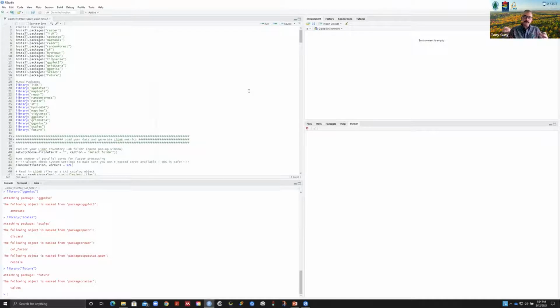So that's something that we've been doing more recently, where you use something called principal component analysis, and you run a PCA on the LiDAR point cloud, basically the grid metrics from the LiDAR point cloud, and use that to help you decide where to put in your field plots to build the modeling. And I can let Dave speak to more of the particulars of that process. It's kind of beyond the scope of today's seminar.